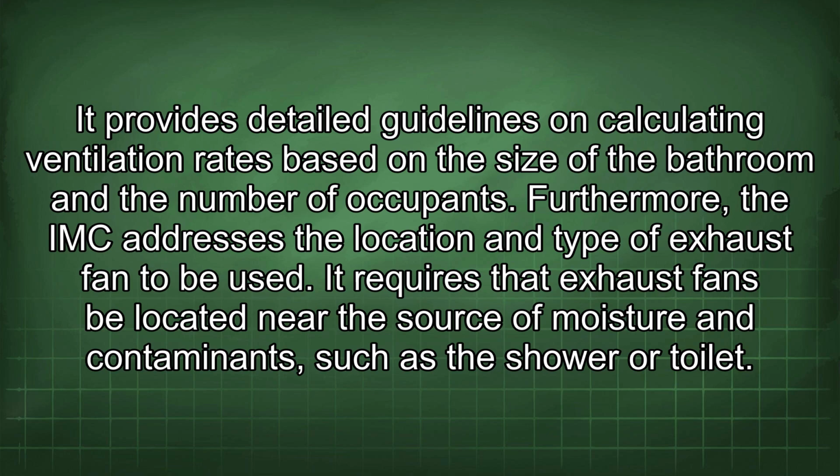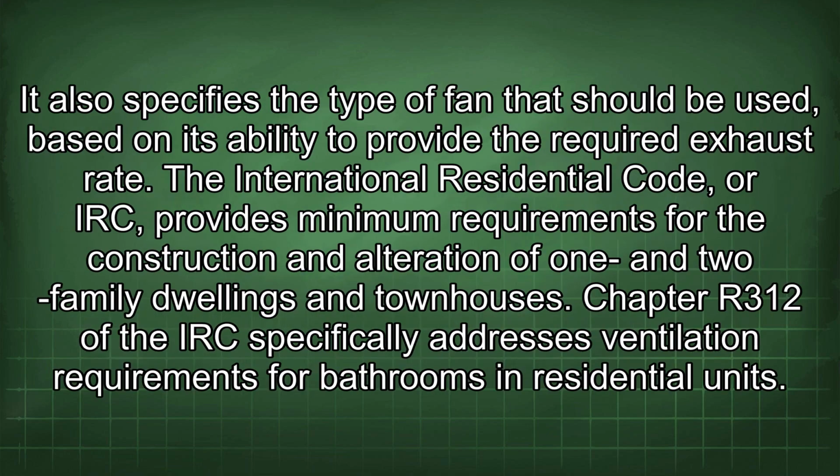Furthermore, the IMC addresses the location and type of exhaust fan to be used. It requires that exhaust fans be located near the source of moisture and contaminants, such as the shower or toilet. It also specifies the type of fan that should be used, based on its ability to provide the required exhaust rate.